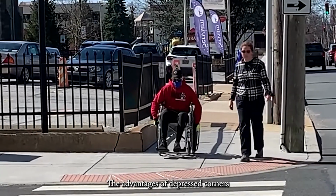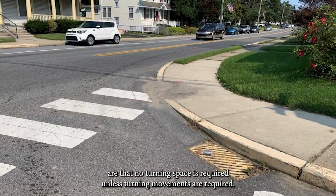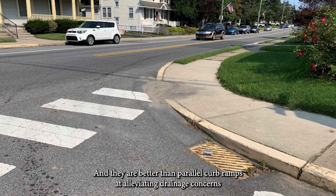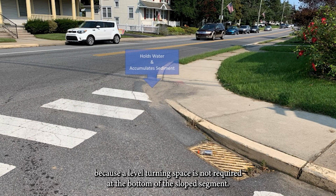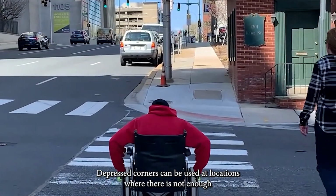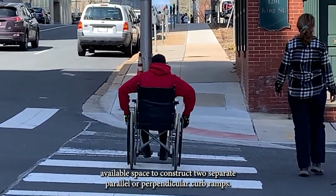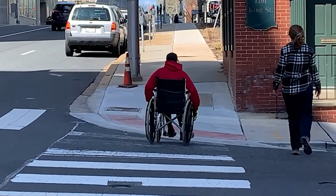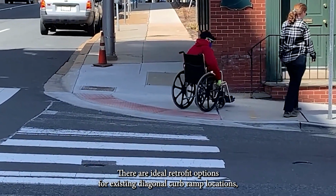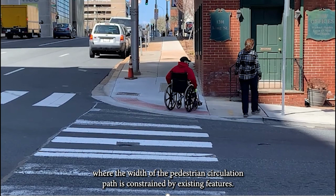The advantages of depressed corners are that no turning space is required unless turning movements are required. And they're better than parallel curb ramps at alleviating drainage concerns because a level turning space is not required at the bottom of the slope segment. Depressed corners can be used at locations where there is not enough available space to construct two separate parallel or perpendicular curb ramps. They are ideal retrofit options for existing diagonal curb ramp locations where the width of the pedestrian circulation path is constrained by existing features.